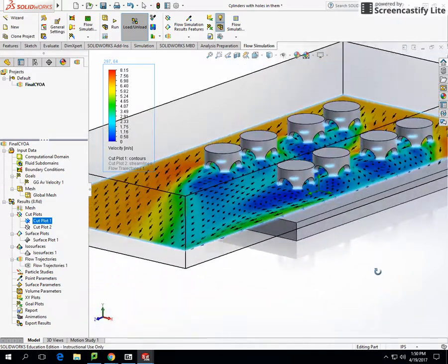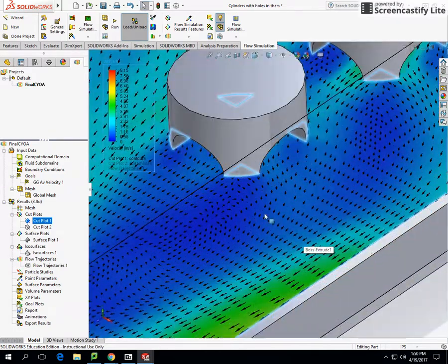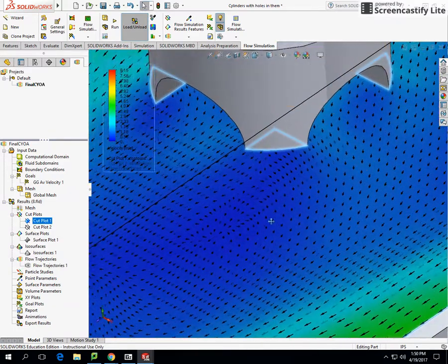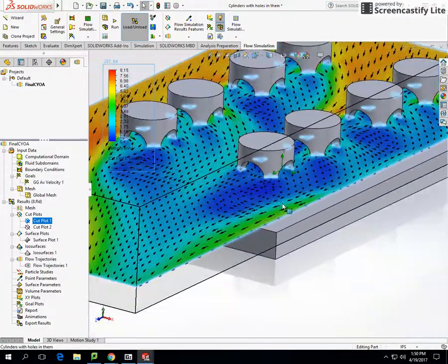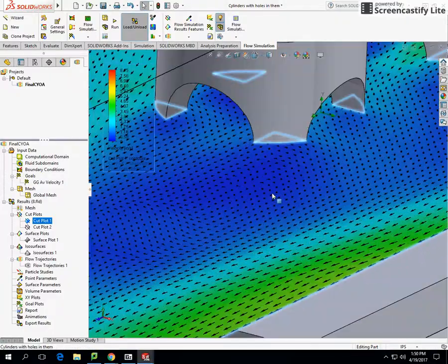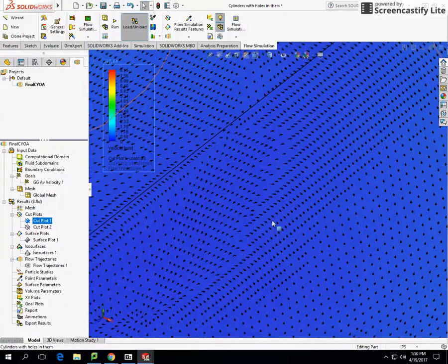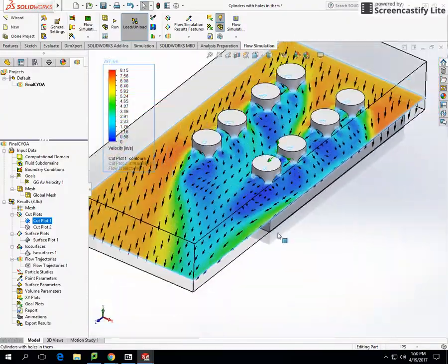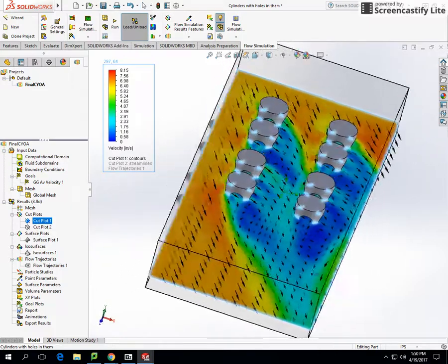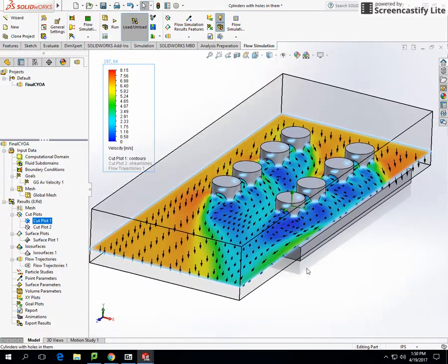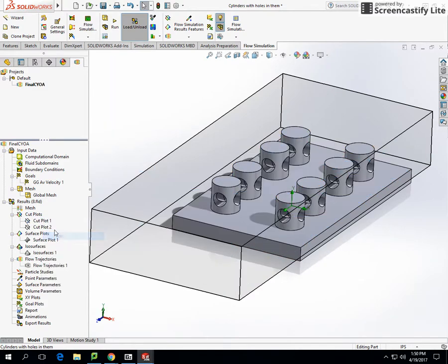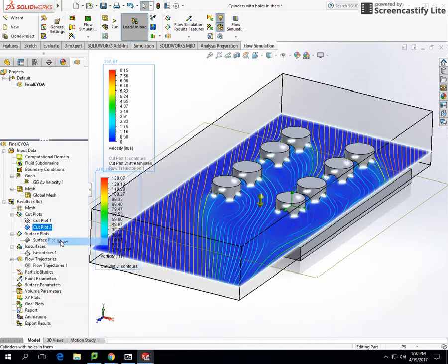And this is going to show you the flow magnitude and flow direction out of these guys. And the arrows will get tighter. You can actually define the spacing of these arrows and the size graphically in the cut plot wizard. And then on here we can see the velocity chosen. I have a different one here. Let's see which one this is.